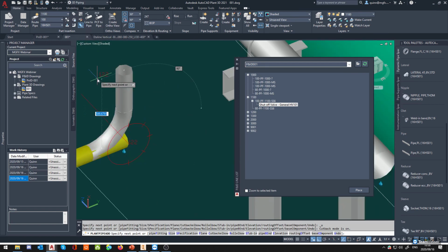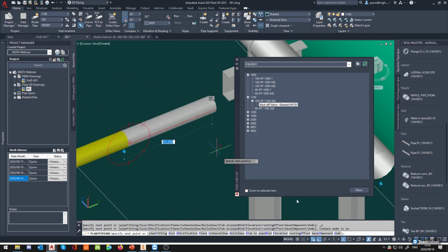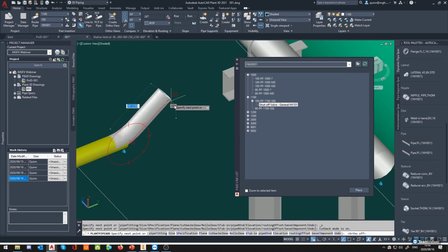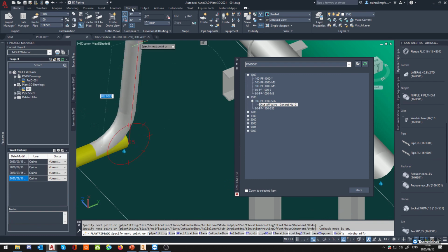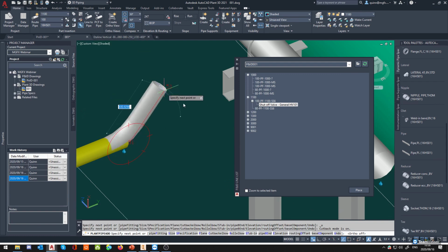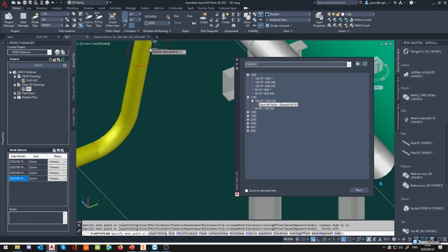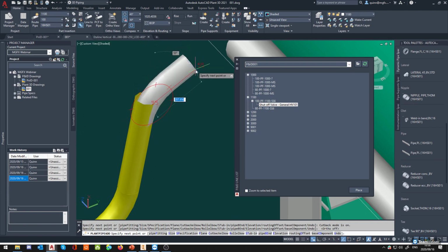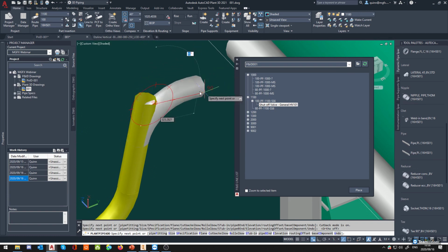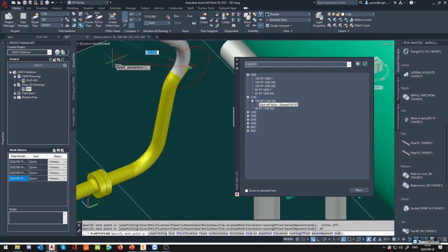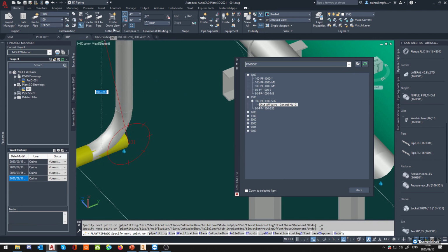What you can do to get around this is use cutback elbows, and that can get around it. If you are still jumping around like this, there's one other thing you can do, which is make sure that your auto mode is not set on. Now, once our auto mode is off, you notice that we can actually lock. There we go. And lock to our different lines. If you want to specify a specific line lock, line degree, you can just use tab and then jump between the different settings. So it's pretty much freeform what you can do from there.